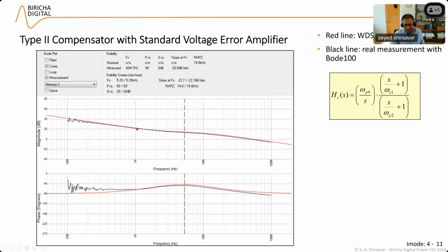So you can see that the gain is flattening and the phase is coming up. Right, and then you hit this pole, and when you get the pole, it's like a low pass filter. Your gain is going to go down at a rate of 20 dB per decade, and then you're going to have 90 degrees of phase loss.